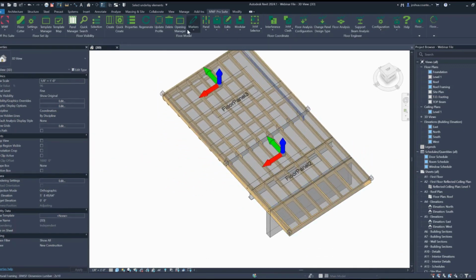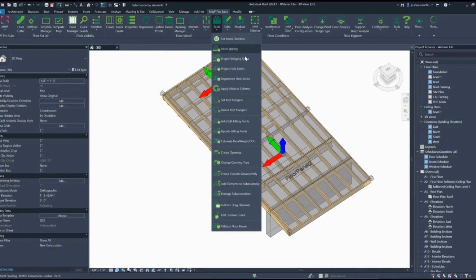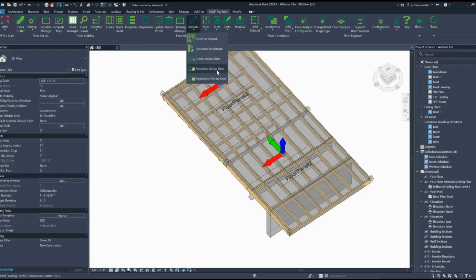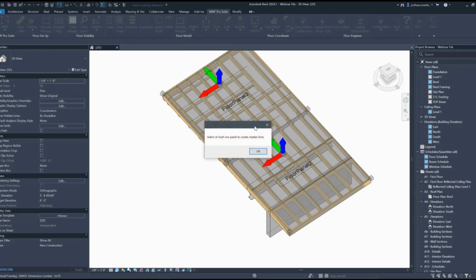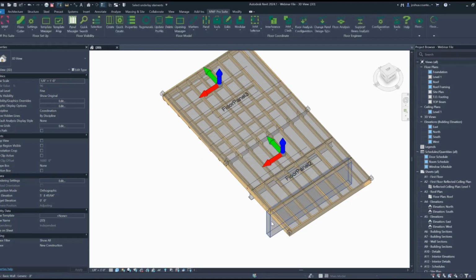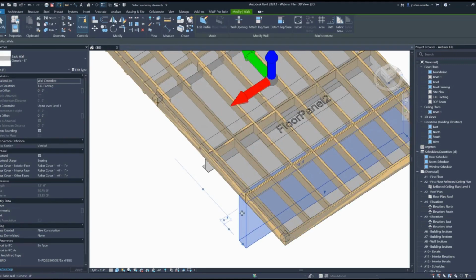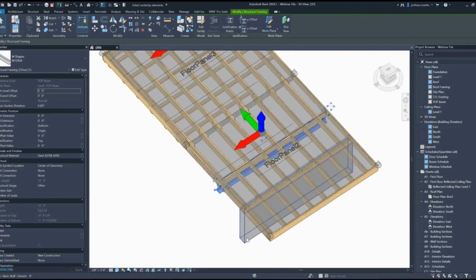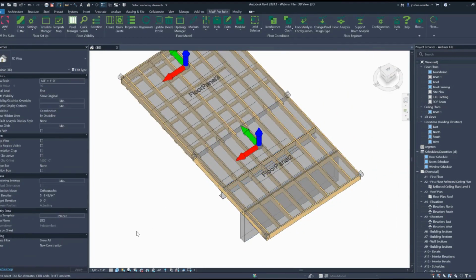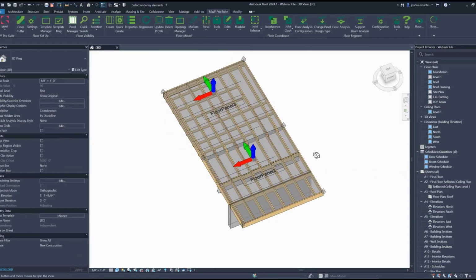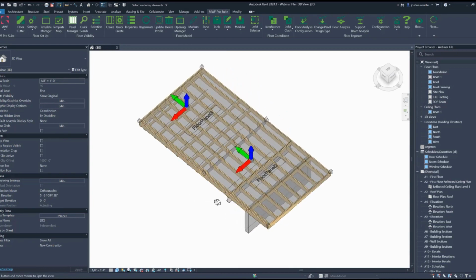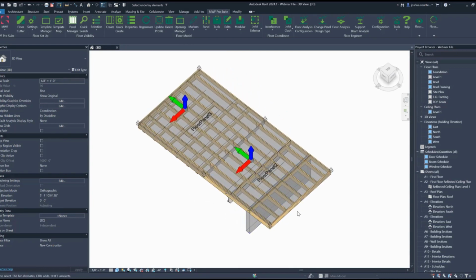So that's a quick overview of how to create project bridging types, project hole series in your floor panels, and also apply or create marker lines and create them in patterns or to align to the walls below, the beams below. Maybe you need it as a spacing pattern or align to a benchmark. And that's a quick overview of how to use that tool.